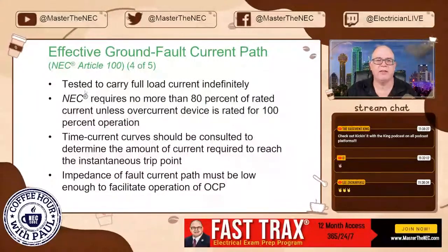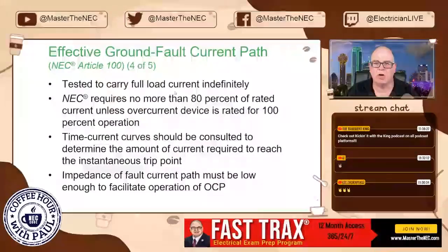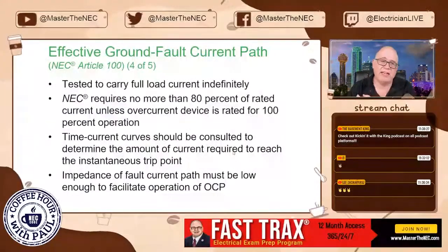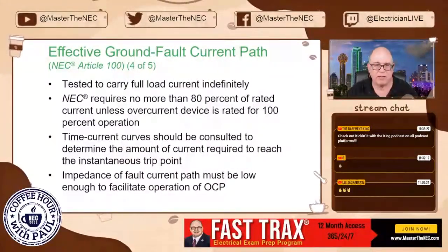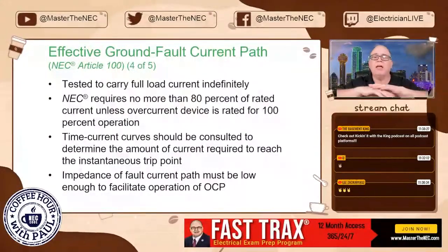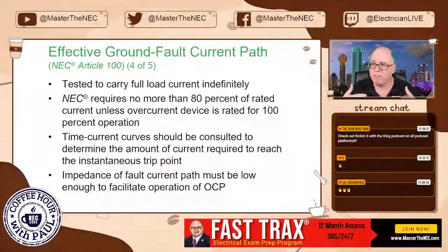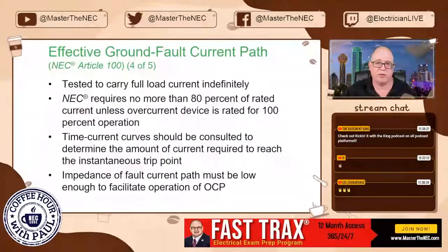All right, tested. So, effective ground fault current path, tested to carry full load current indefinitely. Anytime you have a path and it's all constructed and you're using listed components or fittings that are listed for the type of wiring method you're using, if you've done all that, then it has all been tested. It's all been considered, sized per the NEC and, of course, any applicable standards.